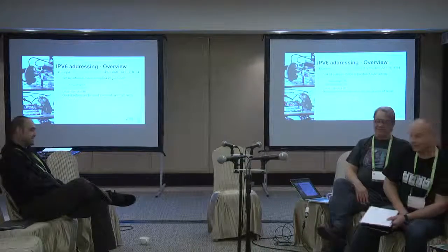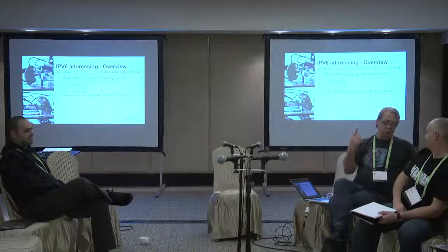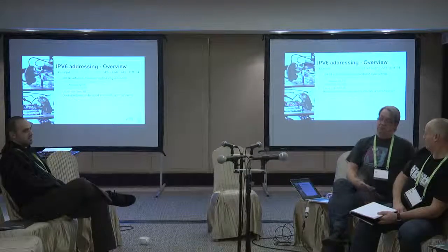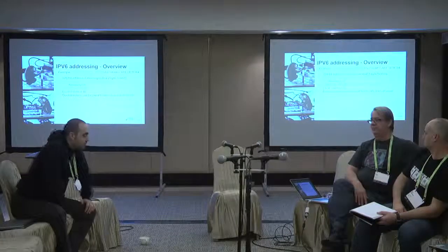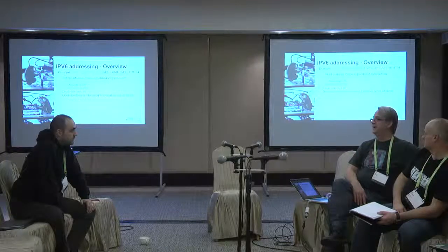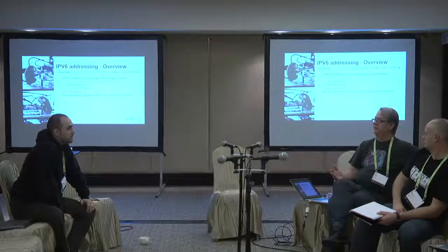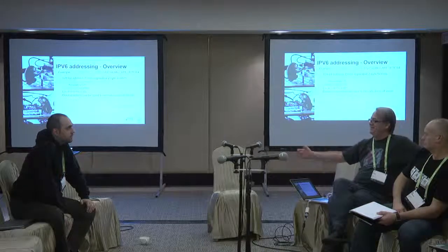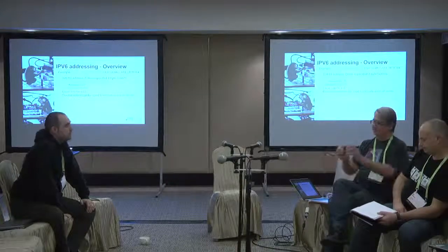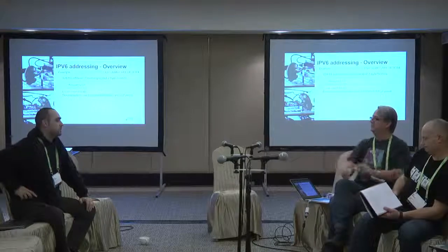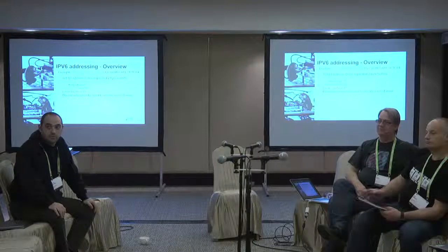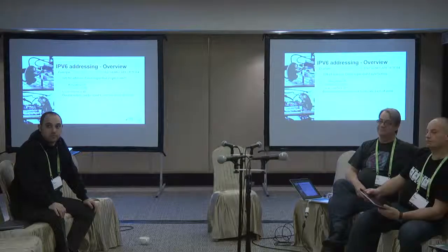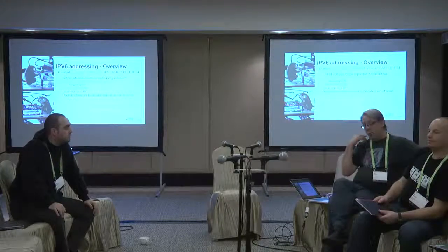Yes. I keep getting asked why we've only got 1 of a particular device in production when we've actually got 10. Well, in this particular case, I've been given the information on how we can reflash the MAC address, so we can do that. But the trouble is, MAC addresses are usually assigned. You're given the top range, and then you just increment the counter and put them on the boards as you produce. Often with the embedded stuff, there is no MAC address, and it's generated randomly at boot. That's easier to deal with.